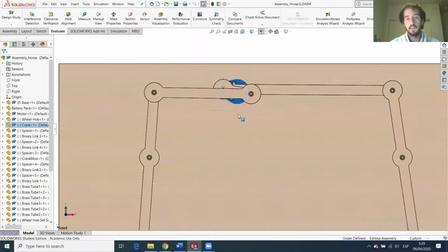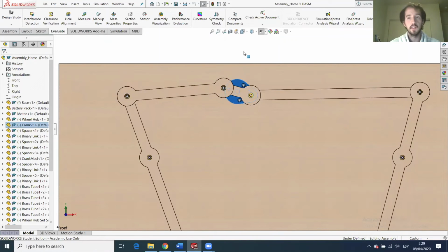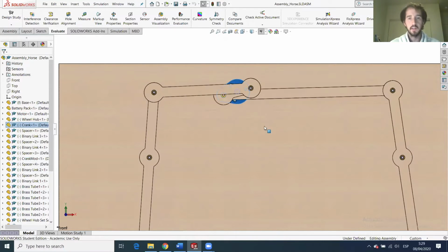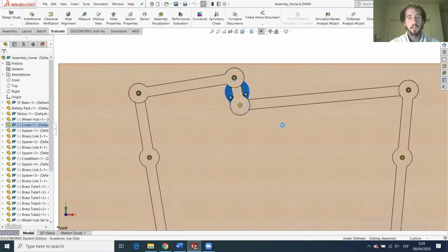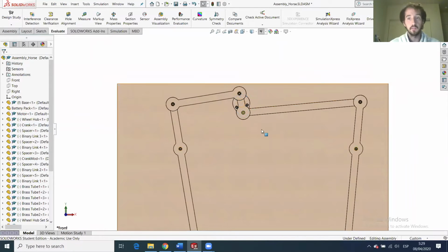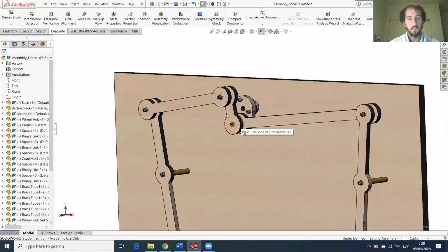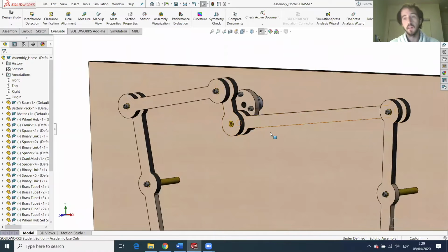But in reality, there is friction, there are tolerances, and that could mean that the mechanism doesn't work as planned. So by adding some bushings and changing the way that we keep the link together, we can improve the performance of the mechanism. So we need to introduce them, and to introduce them, we need to apply a lot of changes. So we will start from the beginning, which will be removing everything that we don't need.